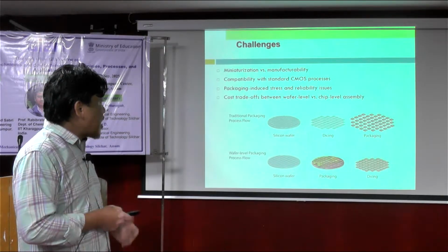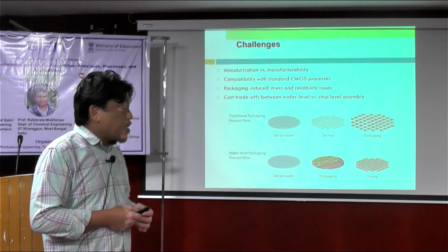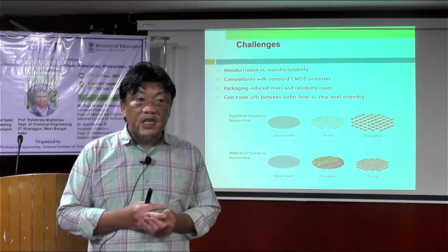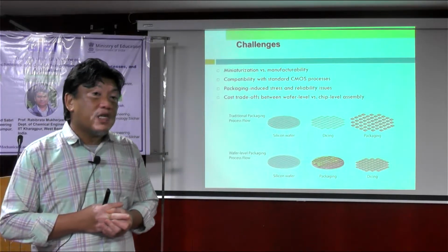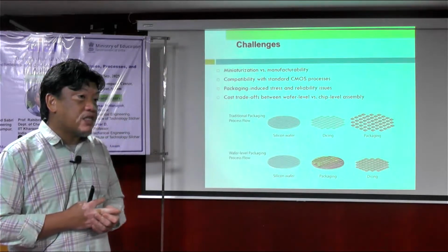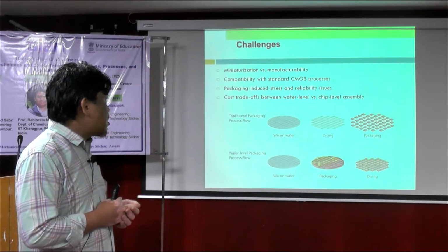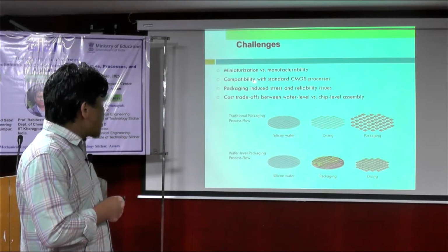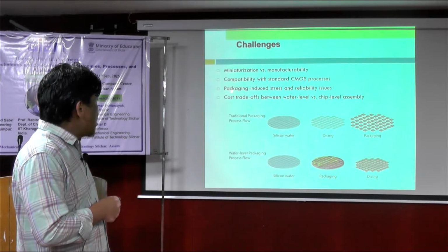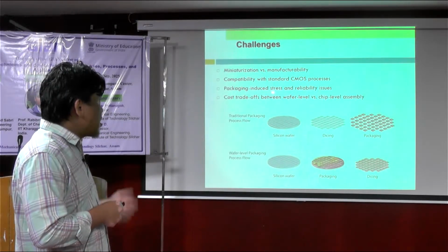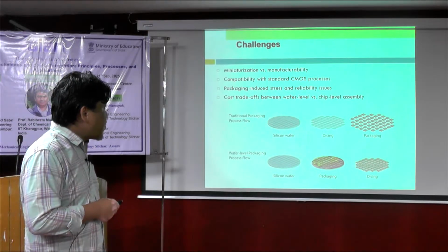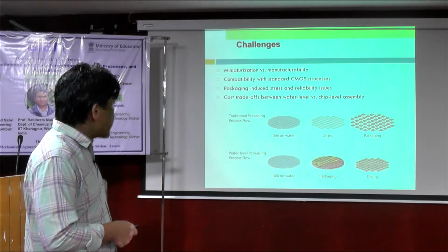So at the same time, it's not just about making the thing smaller, but the manufacturing side, the machinery, the process needs to be able to cater for the needs of this miniaturization as well. Then we will look into compatibility with standard CMOS. These are the challenges, and packaging induced stress and reliability issues and cost trade-off between wafer level and chip level assembly.